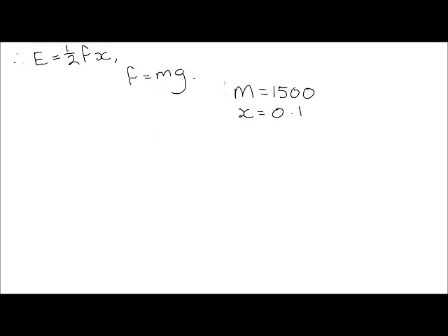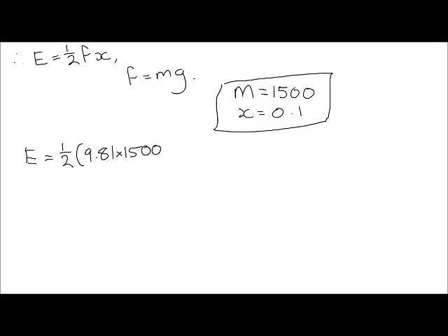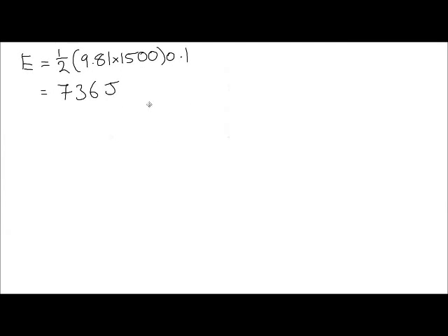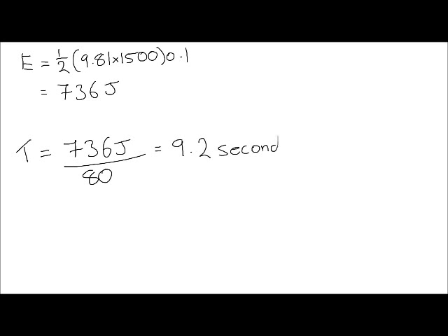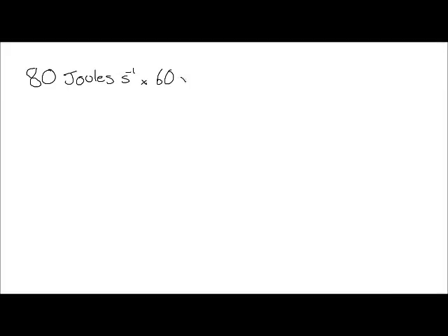Using these figures, we calculated the energy output when one car goes over a speed bump to be 736 joules each time. This means that each time a car passes over a speed bump, it will provide enough energy to power a street lamp for 9.2 seconds. If we assume that every streetlight has one associated speed bump, in order to keep the streetlight on for 8 hours, approximately 2.2 cars per minute must go over the speed bump.